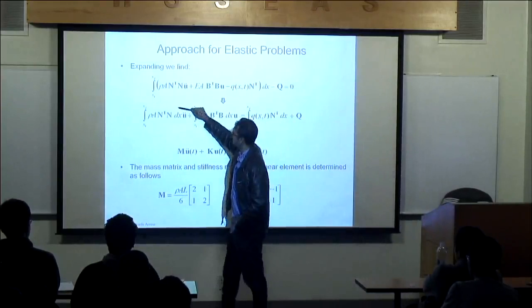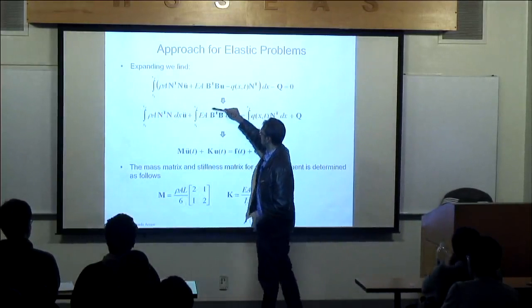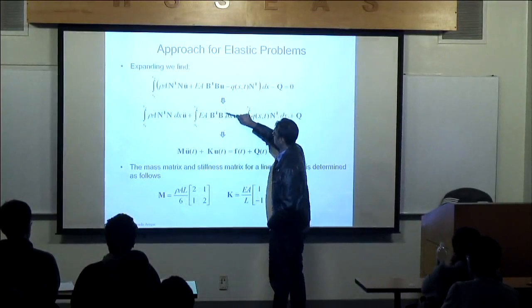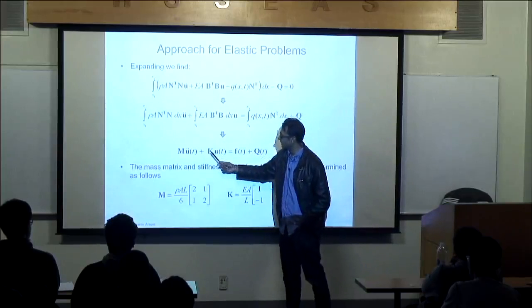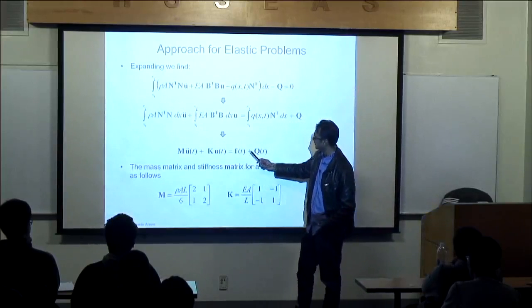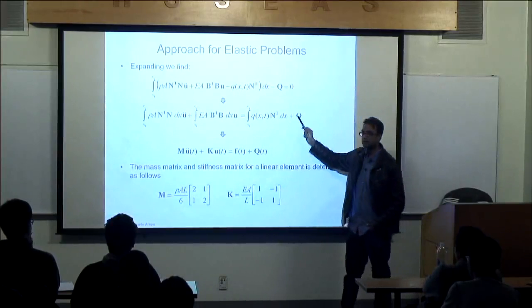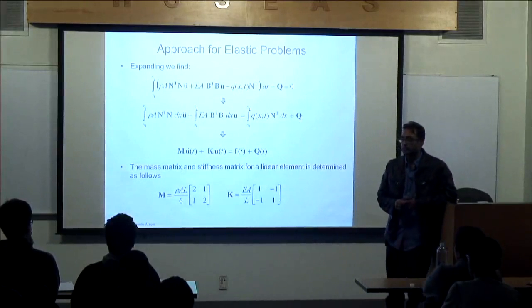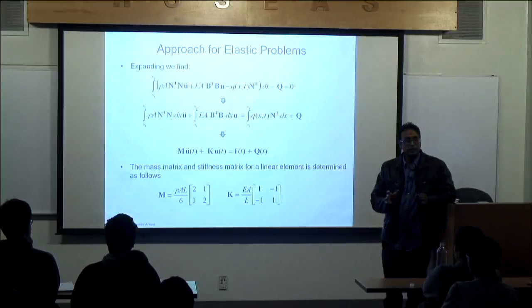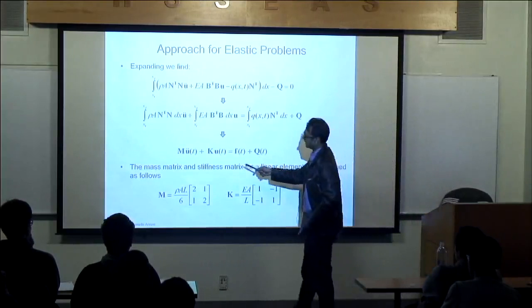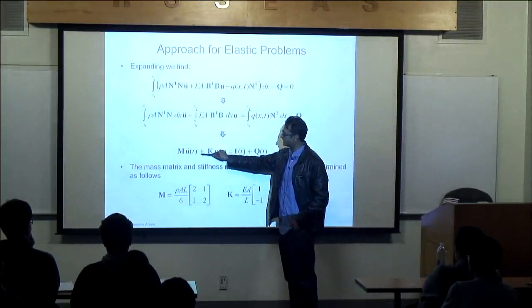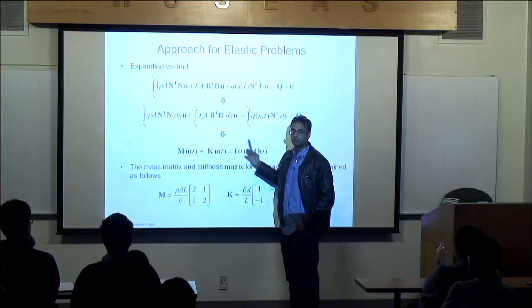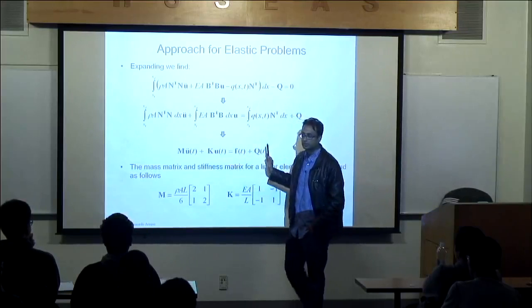Okay. Now I quickly recognize this as my mass. This is my mass right there. That is the stiffness matrix. So that's m u double dot plus k u equals the forces, distributed forces, plus the internal forces. Any questions on that? Fairly straightforward, don't you agree? I can make it more advanced. I can add a damping matrix, plus c times u dot. I can add one if I wanted to. I did not do that in this example.